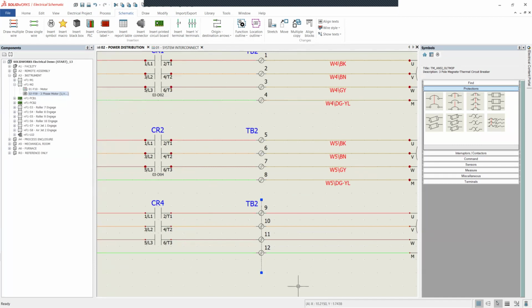So this line isn't critical. I'll delete it. But that's why associating would be critical too. So if something, for example, a terminal block, is already inserted and we don't want a new mark for it, it's one click to make this associated with that terminal block and automatically keep track of all the information that's going on in that terminal block, because that can be built out pretty large, right? So we just want to make sure that all of our information is together, and any changes to that terminal block will be updated in all those different places.